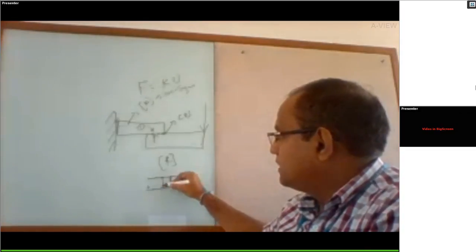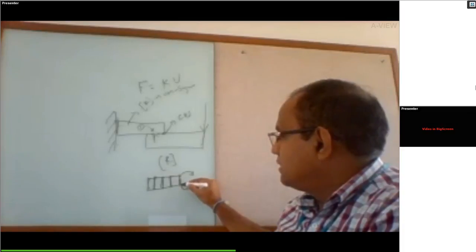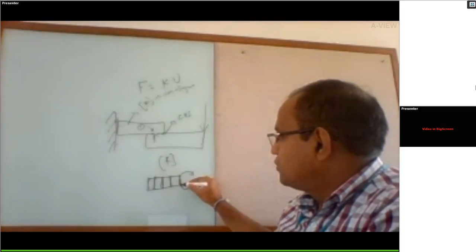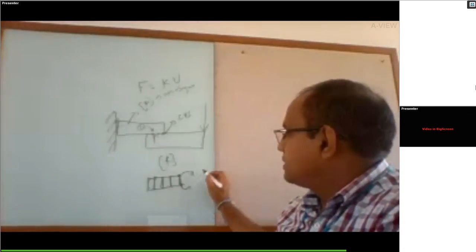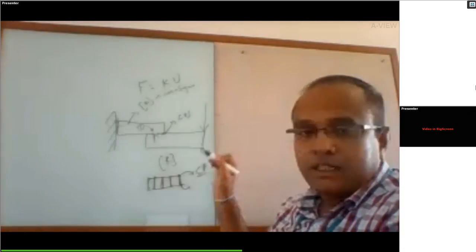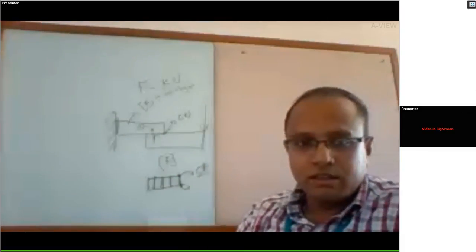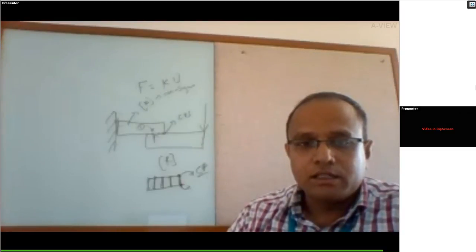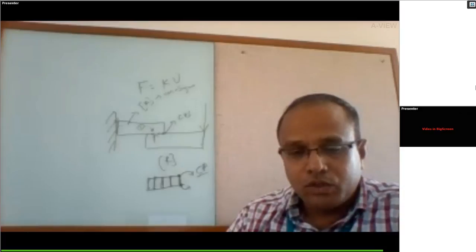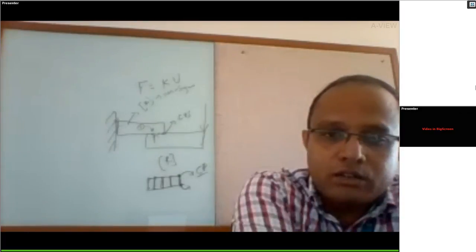Deflection here same, here same, here same. So we are imposing that the deflection of this node should be same as the deflection of this node. That is called coupling. Whereas in CE we will establish a relation between these two things, that we'll discuss. And in multi-point constraints, we won't define any equations, but it's like equations; we won't write any equations, but they will be created while solving.